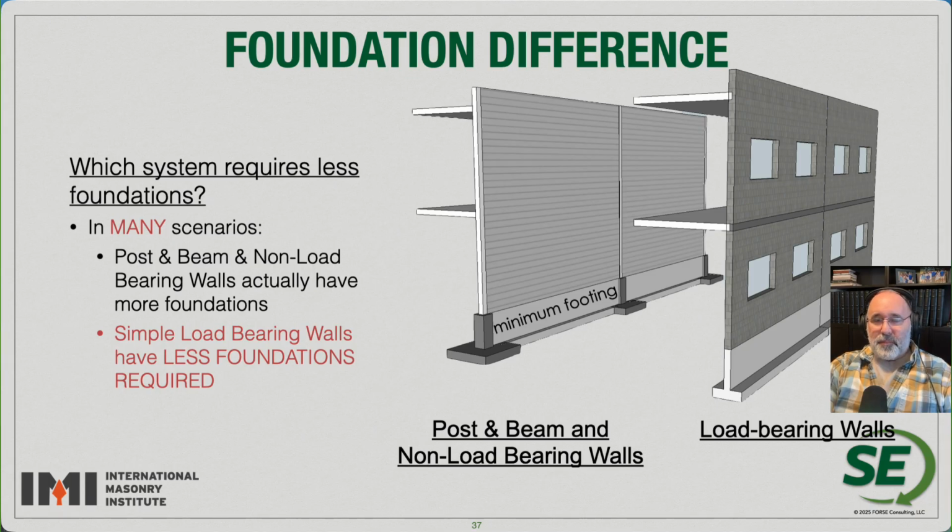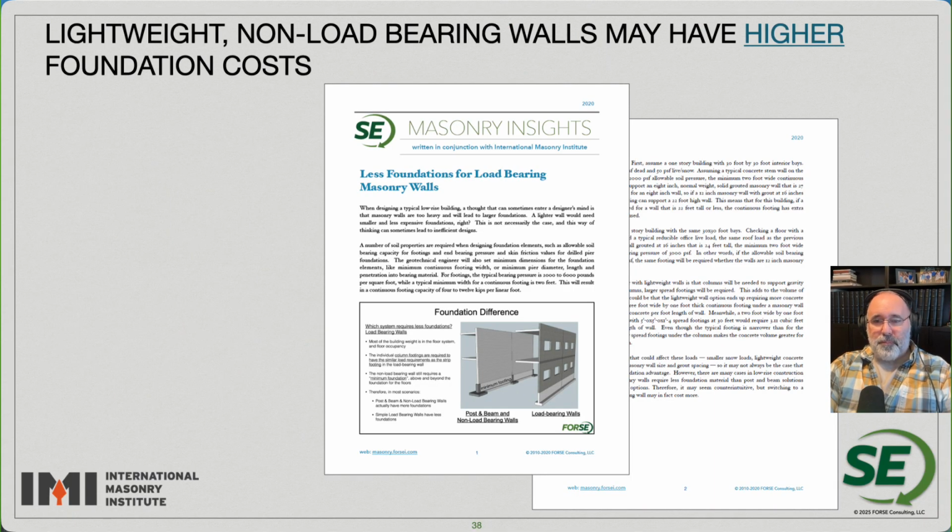So again, which system requires less foundation material? For all of the buildings up to 4 stories, which again, 95% of the buildings in the country are 4 stories and less, we're going to have simple load-bearing systems coming down to load-bearing foundations that use a lot less material. So again, we put everything together here in a paper, and you can certainly download that at